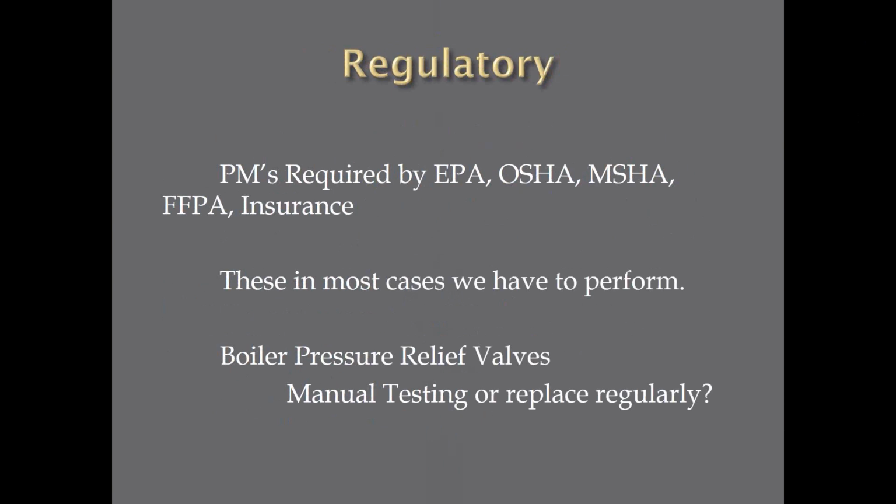Now, I'll give you an example at the facility I came from. We had 2 coal-fired boilers there. Of course, the boilers have pressure relief valves on top. The inspector came in every year and he asked me the same question every year. Have you pulled the lever on your pressure relief valves to make sure they work? And I go, no. And he says, that's required by law, you have to do that.